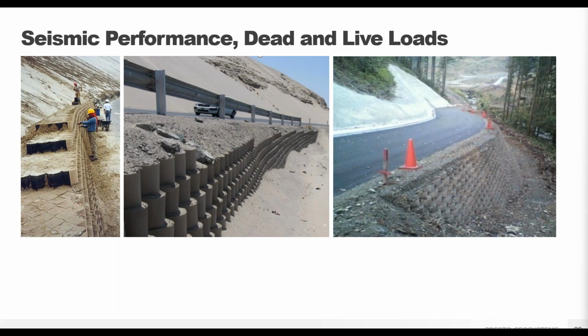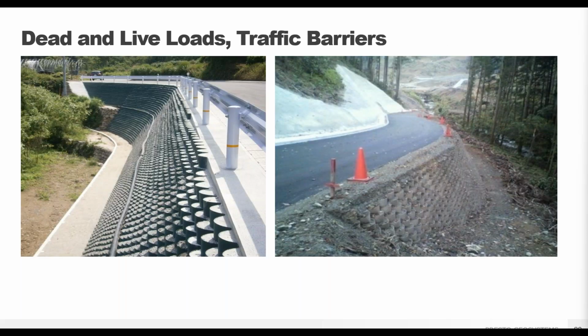GeoWeb walls perform well in strong seismic areas and with live traffic loading. It's always necessary to consider live and dead loads that the wall will experience during construction and over time. Dead loads can be buildings or the soil slopes above the wall. Live loads are for construction traffic and long-term vehicle traffic if the wall is below a road or driveway.